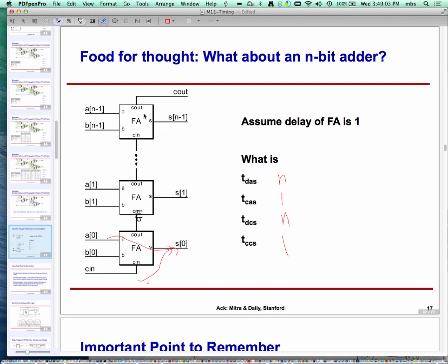Maybe is there a timing parameter for the first change in the input to the last settle of the output? There is none, and the reason is it's not very relevant. It turns out you will see, not today, but next time around, that when we design sequential circuits, this contamination delay is actually a major problem. And the reason is the following, intuitively.